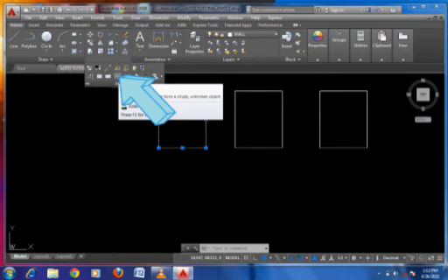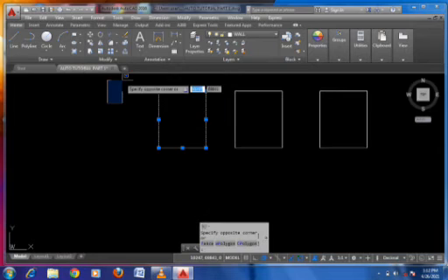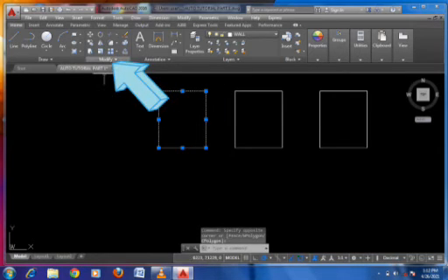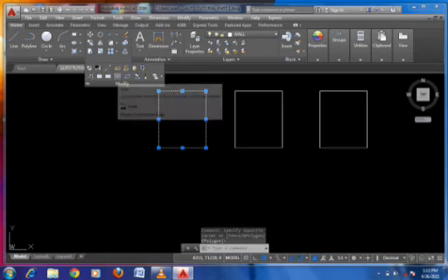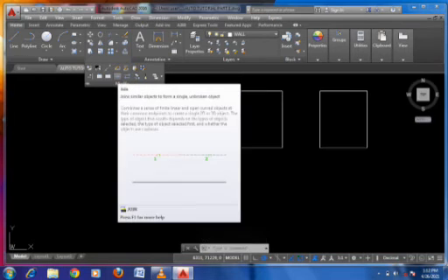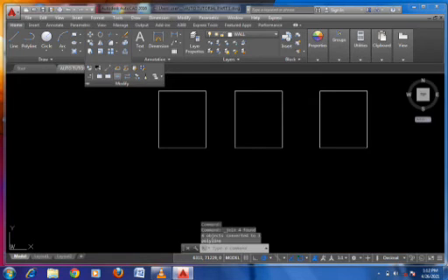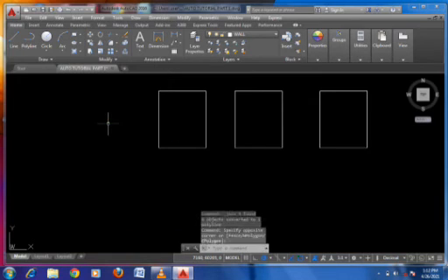It is here, that is your join tool, it is also here, below your modify tool. Once you have highlighted it, you press J, that is your join. We have join here, or you press J, enter, that is the shortcut key to join all the lines together. You can see I've joined them together.